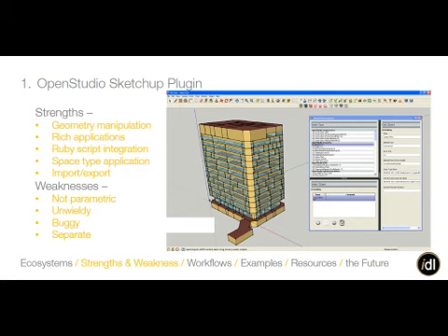There's been a little bit of confusion around that just because Trimble bought SketchUp recently, and now there's SketchUp Make. And it still has some of the Google stuff in it, which is a little strange. But you can still use the free version of SketchUp, and it should run just fine with the free OpenStudio. Yeah, I guess, but it doesn't have a lot of the features that you do the geometry with. It should have all the geometry features. The main thing that you don't get between the free version and the pro version is exporting to different types of 3D geometry files. At least that's the only thing that we've run into issues with.